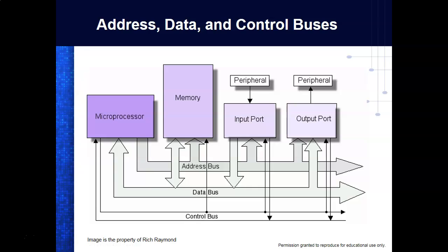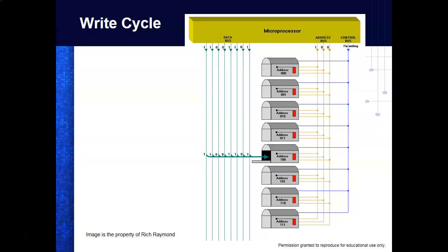A good analogy of this would be this diagram that I drew, by the way. I've got a 3-bit address bus. So 3 bits means I can select 8 different things, and we looked at that. So right off the bat, the size of the address bus: here I'm using 3, so that means I can select 2 to the 3rd. So that's 8. So I've got 8 mailboxes down here.